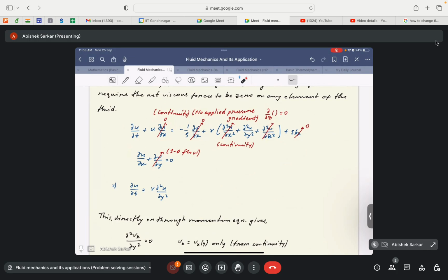Okay, since there is no body force term that we are considering in this case, and also there is no point of considering the body force term along the x direction for this particular problem. So rho bx equals 0. So we are only left with two terms, that is the unsteady term dou v by dou t and the viscous force term, mu dou square v by dou y square.